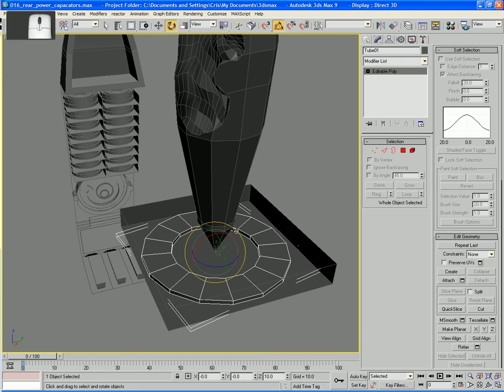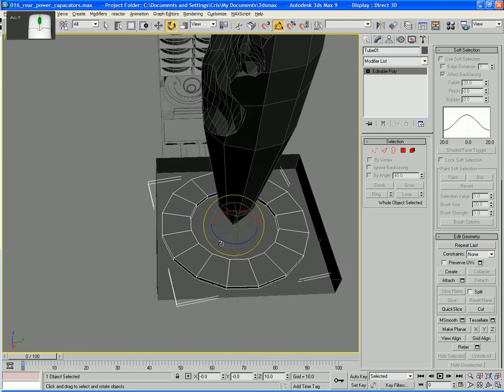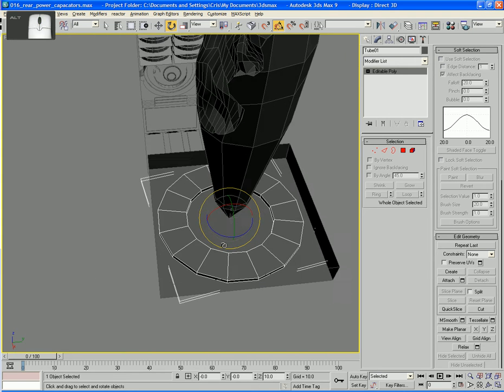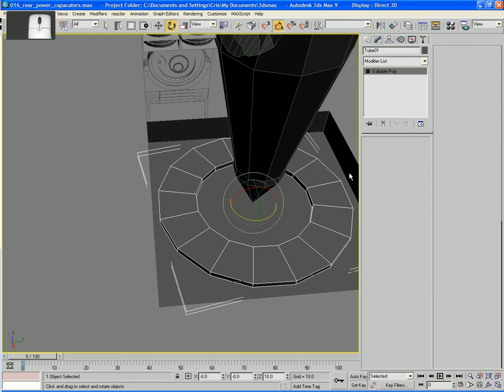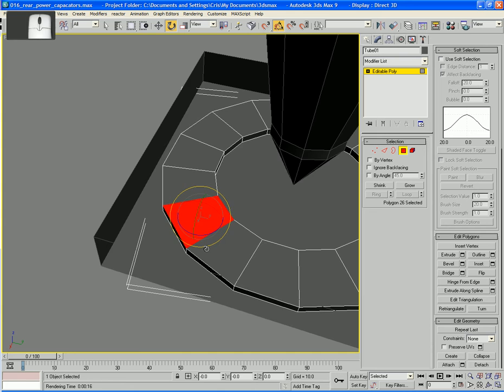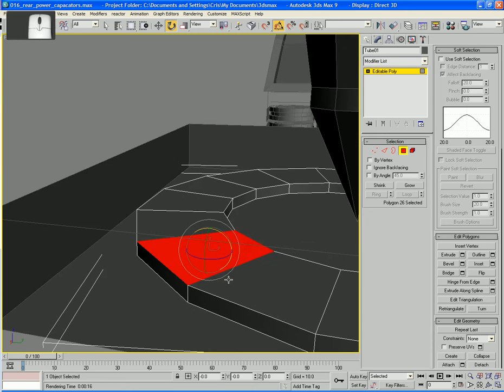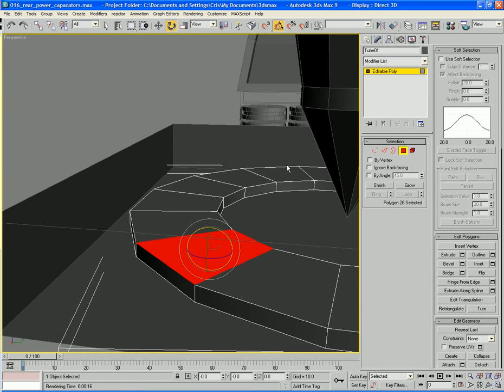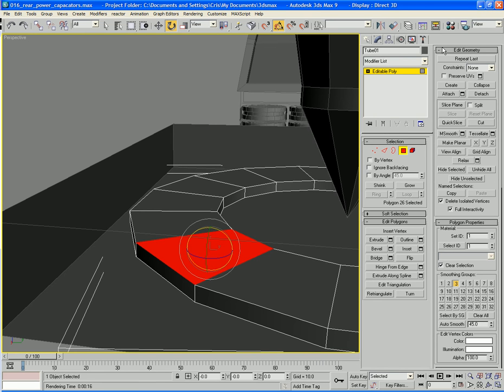Now, what I'm going to do is build our clamps that are going to kind of hold our crystal in place more or less. And I'm going to start them from this piece here. So zoom in on it. And turn off soft selection because it always bugs up my viewport. Detach to element.